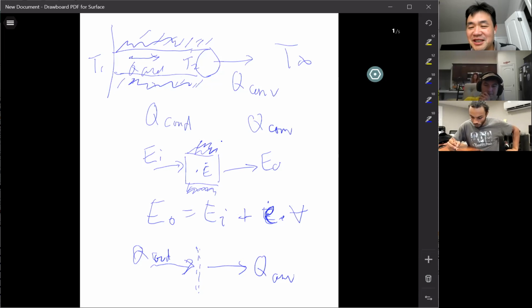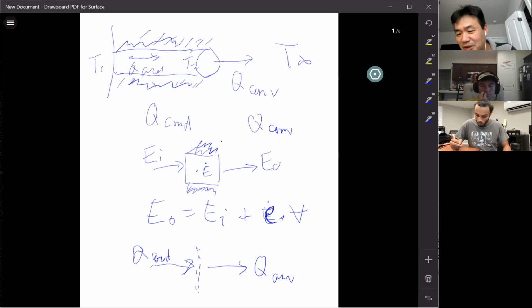If you just want to see energy transfer through an interface, through a surface, then whatever the material is, or air, it doesn't matter whether there is generation in the conduction in the material or not. On that cross section, on that surface, there's no volume. If there's no volume, there's no energy generation. When you go through that surface, energy in has to be equal to energy out.